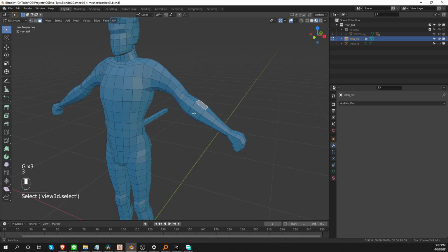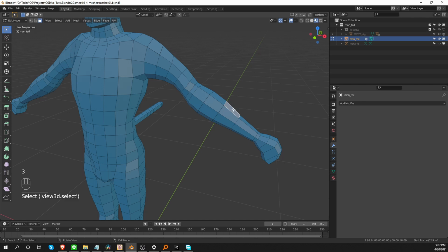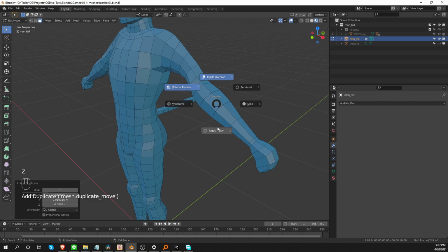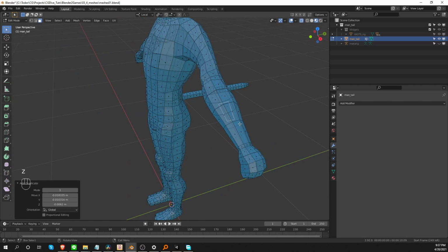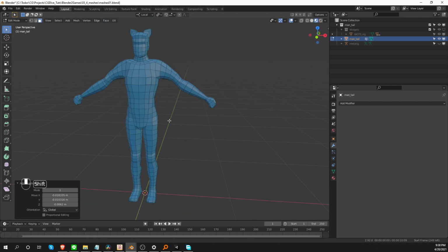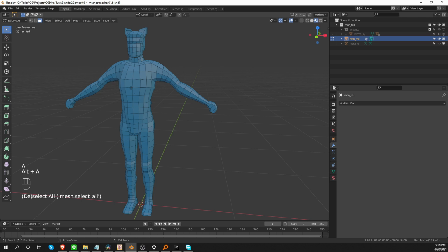Okay, sometimes, for example, I can select a polygon and again Shift D and duplicate it, and then I'm going to move it inside the mesh. So that is something else that you could do by accident. And now if I go to X-ray mode, I'll be able to see this polygon, but without X-ray, it will be invisible and hidden behind the geometry of my character. And now I can run merge by distance, and that will solve some of our problems here, but it will not correct this disconnected geometry that is inside my character.